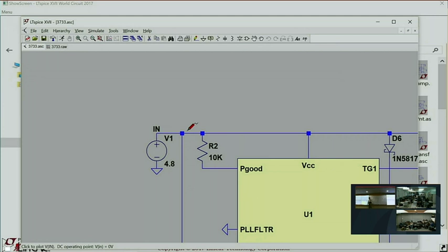That's not the story in voltage mode. In this thing, if you get an abrupt change in voltage here, you have to change the duty cycle, which means you have to change this voltage, which means you have to slew the voltage on the compensation capacitor. And that can take milliseconds. On this compensation capacitor, you just have a voltage there. It says how much peak current you have. Let the flip-flop figure out the duty cycle. You don't have to change the voltage on this capacitor for that.